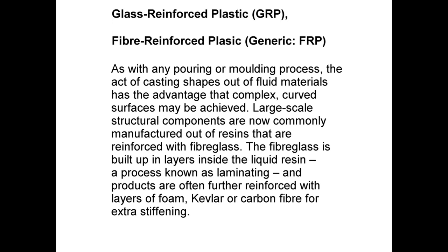The terms that you're probably already familiar with are GRP and FRP, glass reinforced plastic, which is what it originally was patented as a material, and more recent terminology is fibre reinforced plastic, because the reinforcements can take a variety of forms. So it's not fiberglass. Fiberglass is one of the reinforcings that is used in FRP. Fiberglass gave the name glass reinforced plastic.